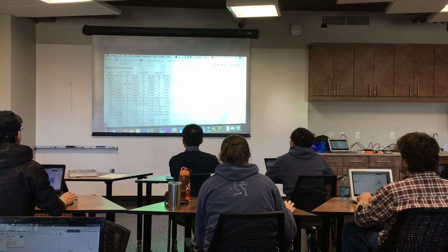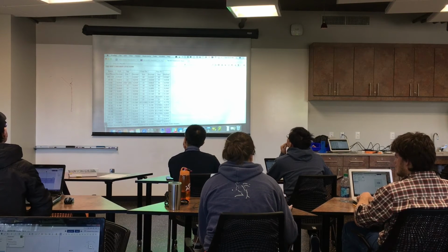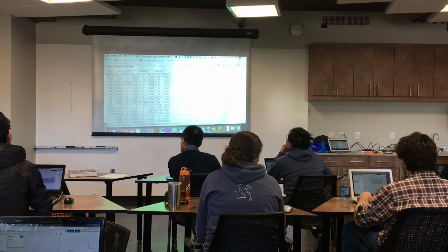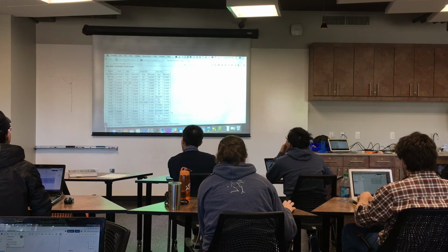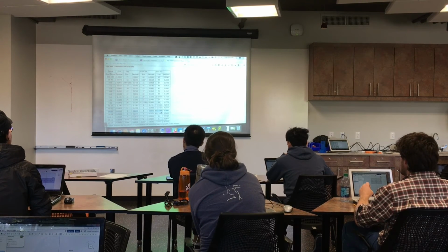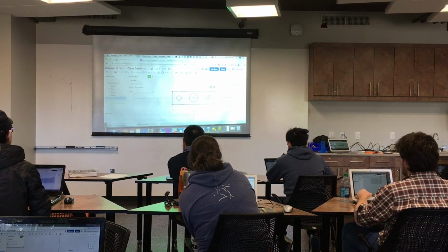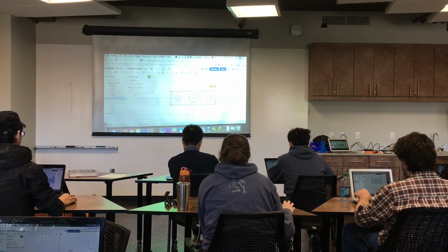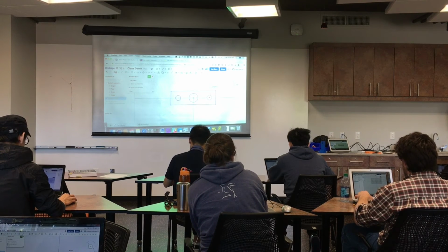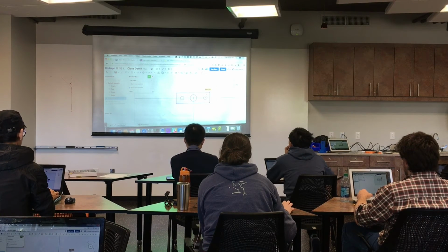Physics.mtu.edu, tap and clearance drill sizes, and you get this chart. We want 1/4 20, which is right here, and we want a free fit, which should be 17/64. Here's the cool thing: we can go back here and you just type 17/64 and it does all the math for you. You can also, let's say we want to do this as a 5 millimeter hole. You just type 5 mm, enter, and it does it.